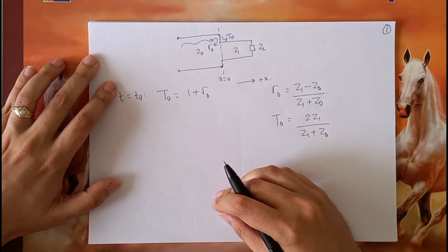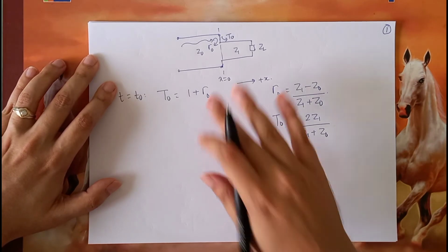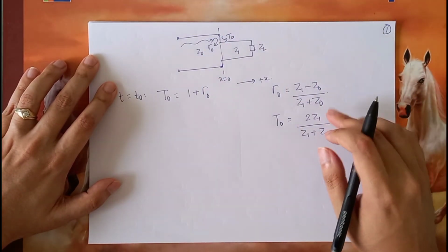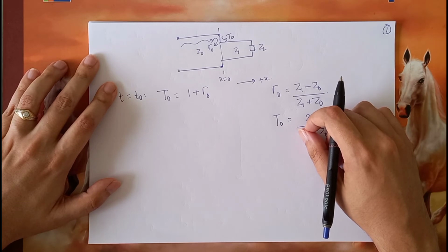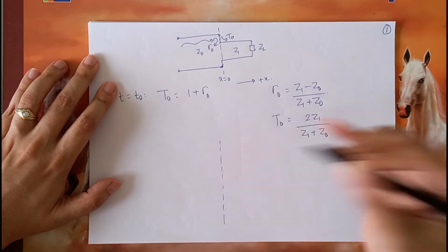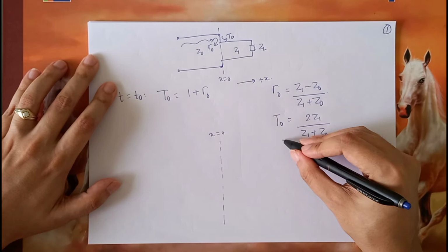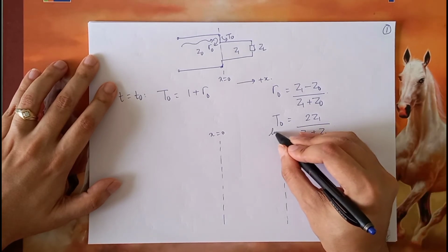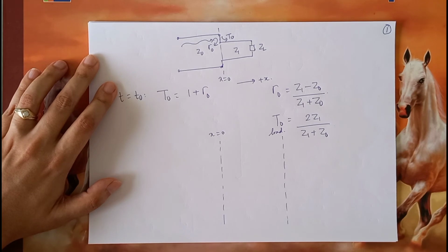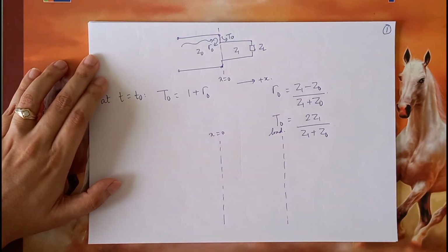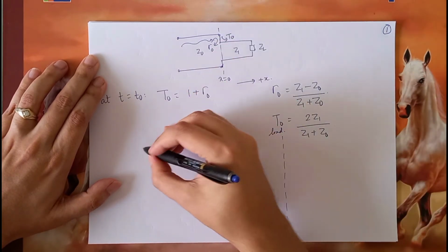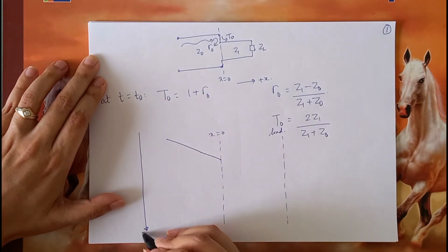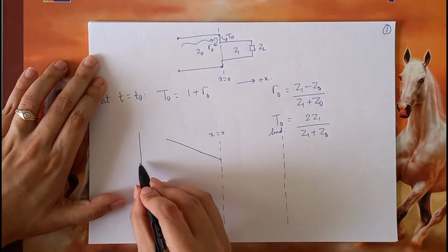Now, so far, whatever has happened, let us try to denote that by means of a bounce diagram, which we already know how to work with. So let us say this is the point where x is 0 and this is the load. Suppose from the source the wave starts at time t equal to 0 and it hits the boundary at time t equal to T0. So let's put the time axis over here. So let's say this is T0.